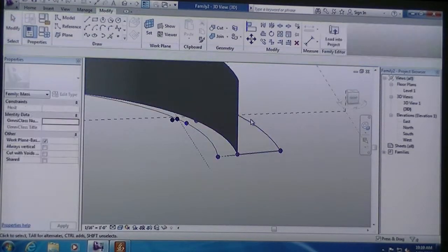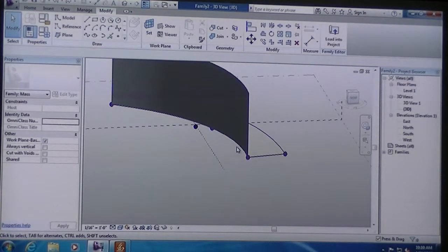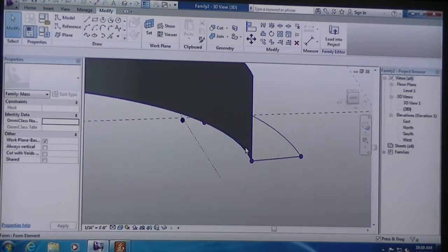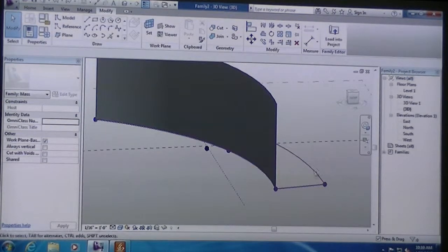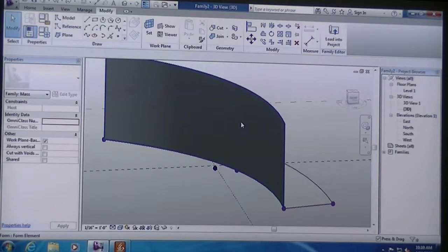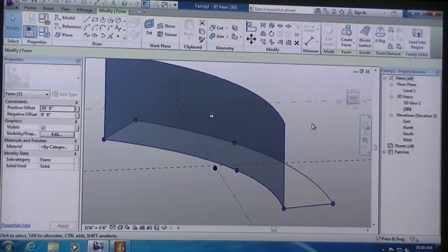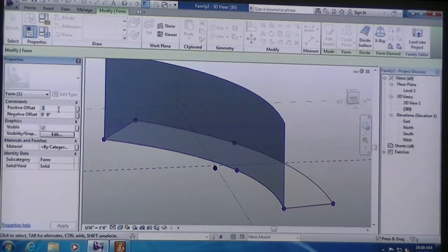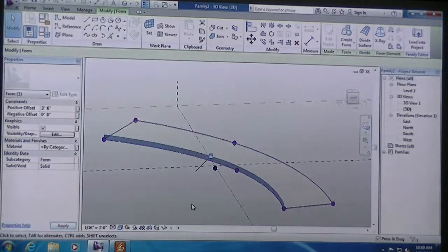Well, railings would probably be something you would do last. But anyway, you can extrude that up, and maybe if this form was parametric, I could test that out a little bit later. But basically this extrusion that goes up, I want to extrude it as a positive offset and change that dimension to 3 foot 6 inches. That's the height of a guardrail.